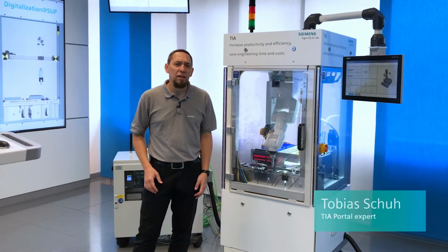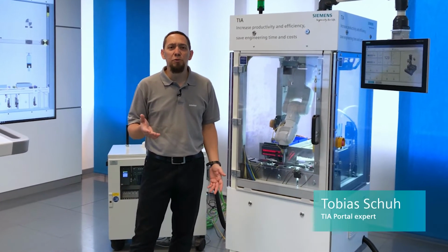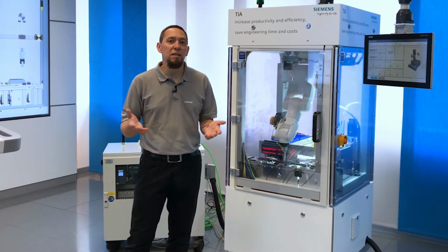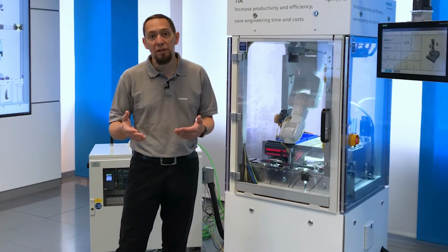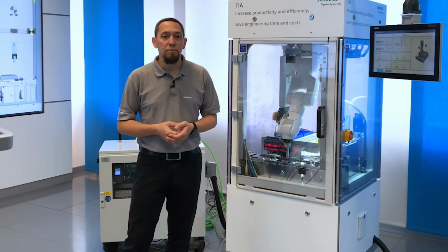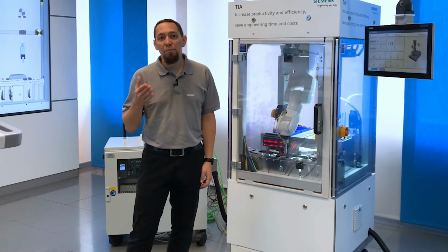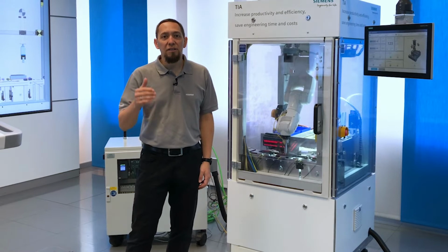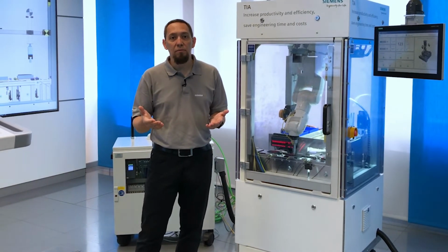Do you have sporadic and unpredictable behavior in your plant? For this we have the trace function, which is supported in our SIMATIC controllers and Drives frequency converters. In these devices you can configure, start and then evaluate the traces. With TIA Portal version 16 and the project trace, you now have the additional option to start the individual traces on different devices simultaneously and evaluate them afterwards together in a synchronized manner.